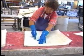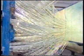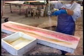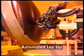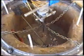These fibers come in many forms, including strand, tow, fabric, pre-impregnated or pre-preg tape, and preforms. There are numerous methods of producing composite parts, with the primary types being manual layup, automated layup, spray up, filament winding, pultrusion, and resin transfer molding.